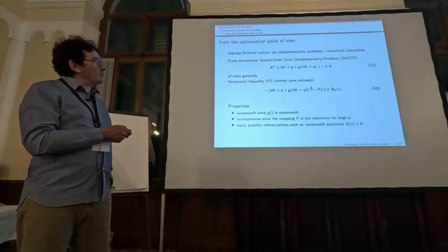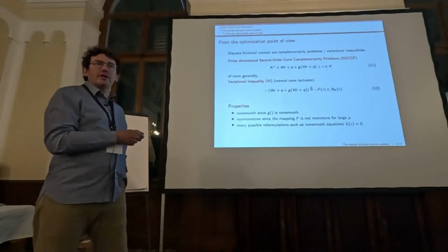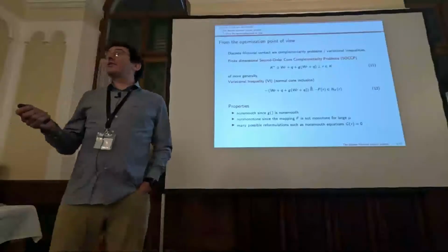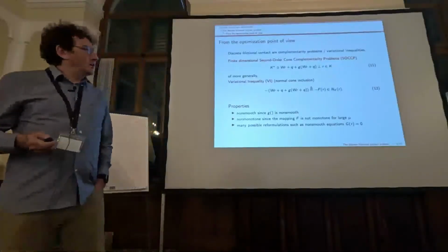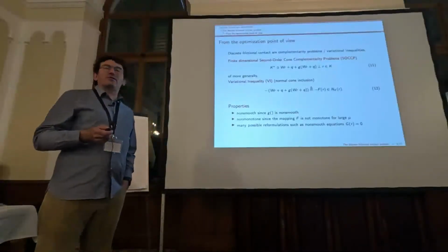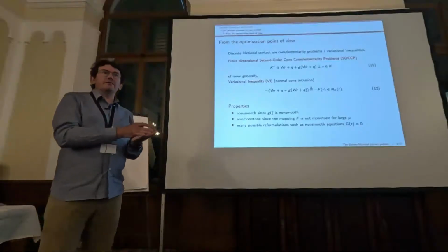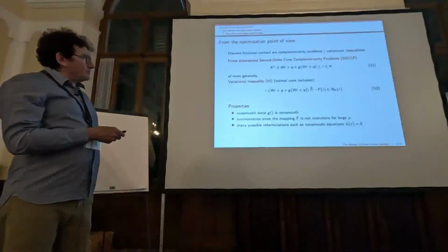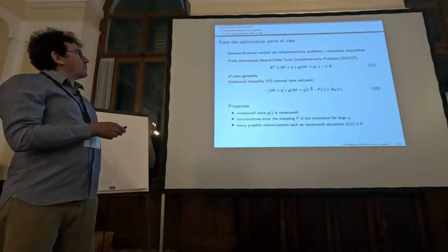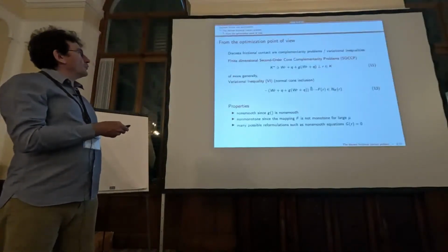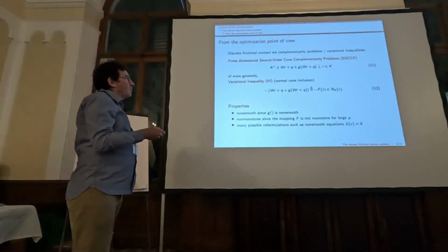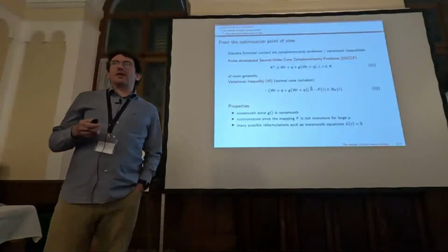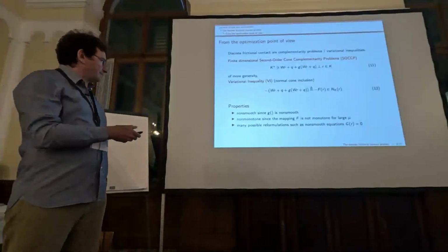If J is equal to 0, we have a monotone variational inequality, everything is fine, but we are in the case of associated friction problem, which is not really useful in practice, because when you slide, then you take off at the same time, so you have dilatancy. So the problem seems to be a nice problem from the structural point of view. We have a second order cone complementarity problem, but there is no result in the literature to prove that we can have a convergent algorithm to solve that.